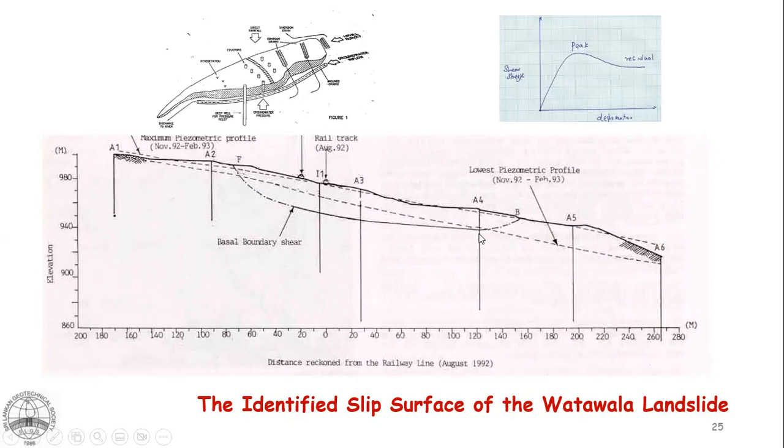So that's why, through the directional drilling technique, they did a computer controlled drainage solution following this path. Under that, 13 HDPE drains were installed. So as the water table attempts to rise during periods of heavy rain, the water has a clear escape route through that.